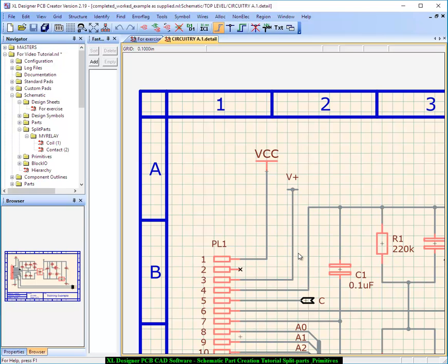If the netlist is extracted in hierarchical mode, then all signal names are local to the sheet in which they reside, unless they have been defined in the power names table, at which time they become a global connection. To maintain connectivity across hierarchical sheets, you have to use block I/O ports, and that will be the subject of another tutorial video.